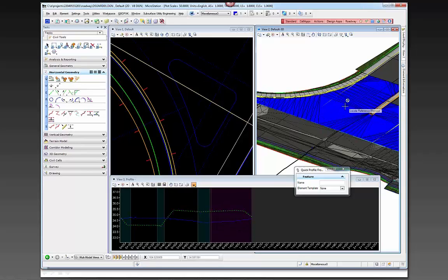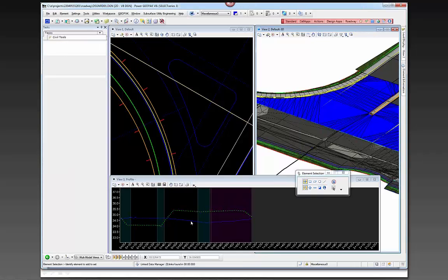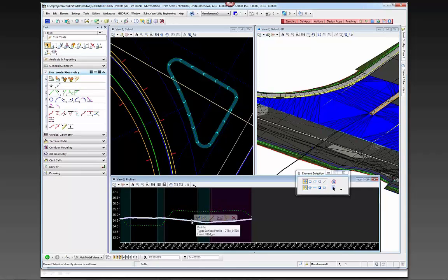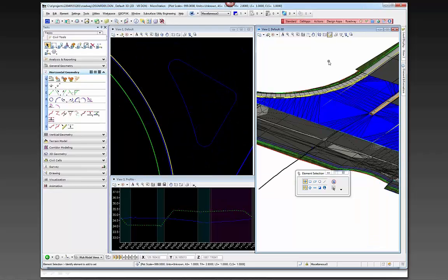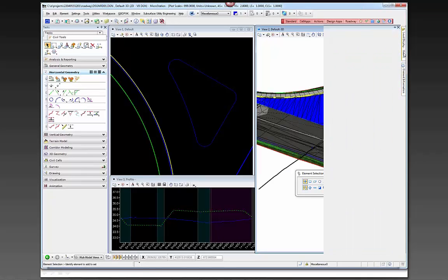of that. Once you have that profile, you can make it a little smoother if you want to, or you can just set it as the active profile. And what you'll get is a 3D line string that gets drawn out here. Possibly. Sometimes it doesn't get drawn on the right level, and I'm not sure what level. I think it may go on level default actually.